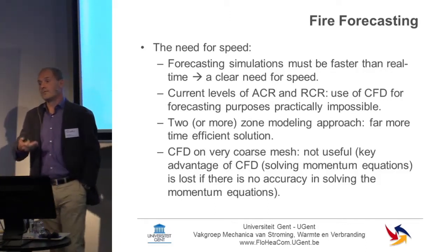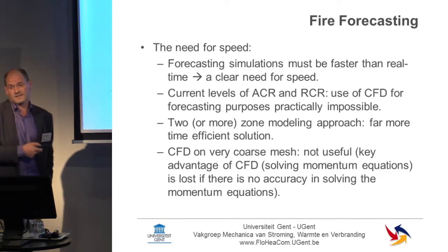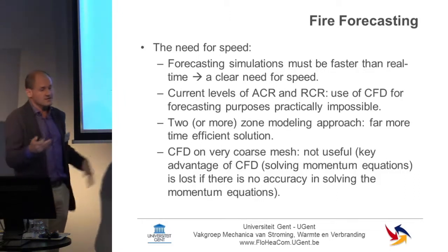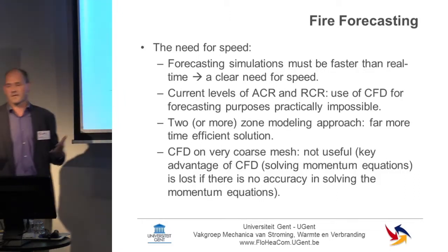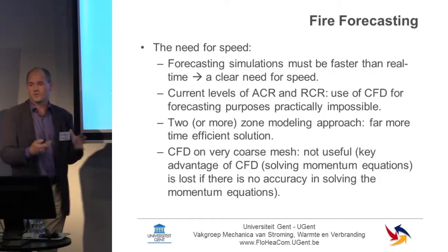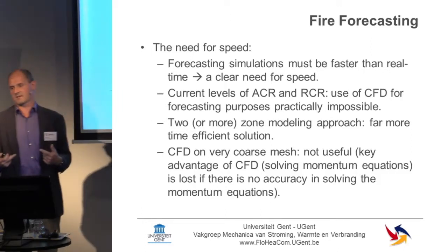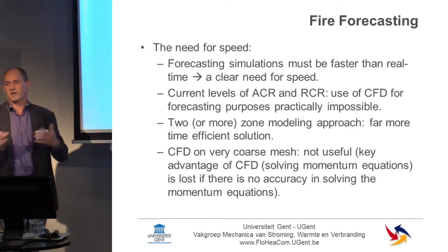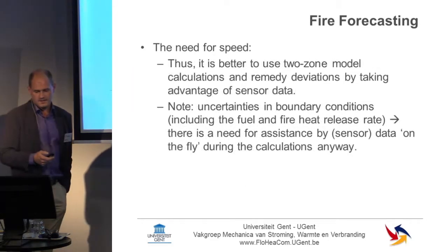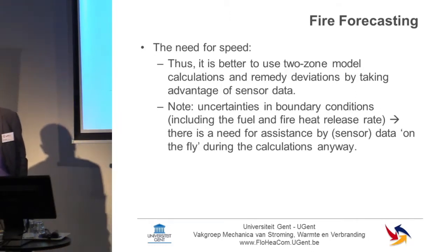So it's much better to do a number of zone model computations, and you know that you'll be working with a limited number of zones, than to do a poor CFD, because you could very naively say, okay, we're going to do a CFD calculation on a very gross or rough computational mesh. It's not a good thing, because you need to calculate very accurately. So, in this context, it would be preferable to look at zone modeling.